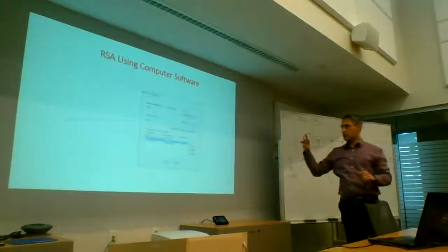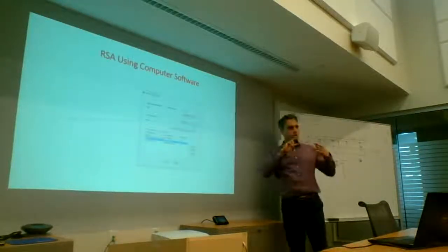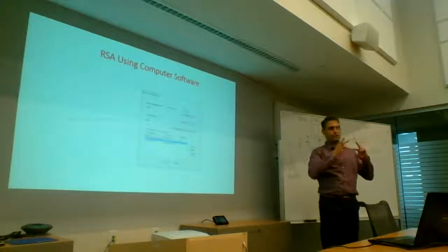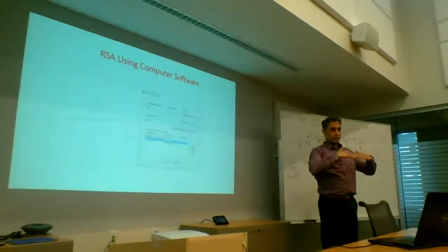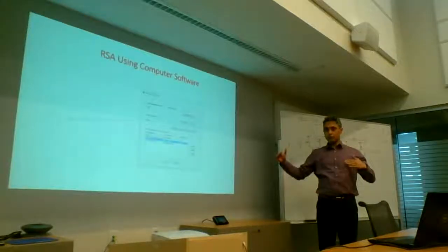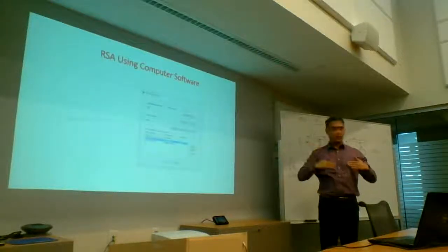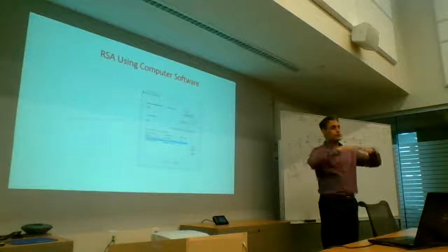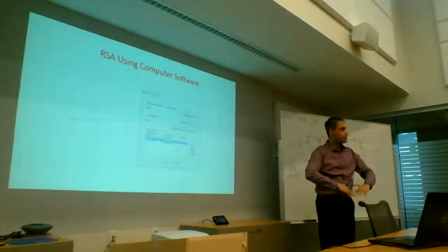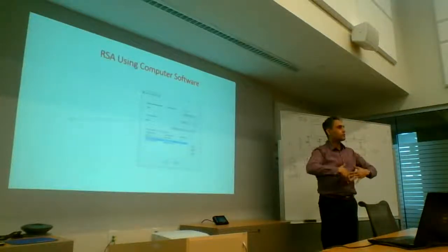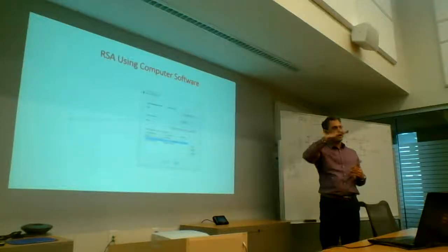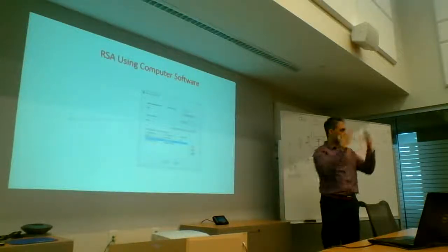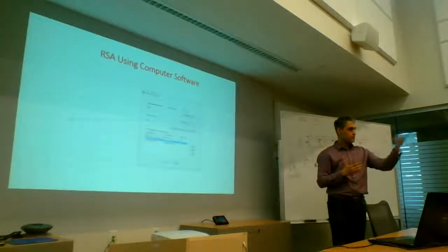So in the seismic combination, when you're doing dead plus seismic, either you apply the vertical response spectrum in your model, or, if you don't, the code says use 25% extra downwards and 0.8 to account for vertical excitation. So you're artificially making your dead load lower and higher to account for the vertical excitation.